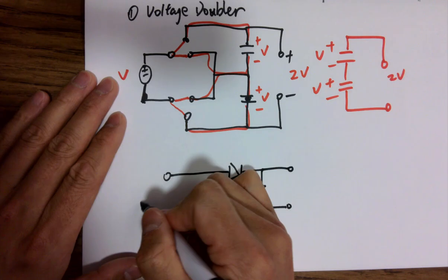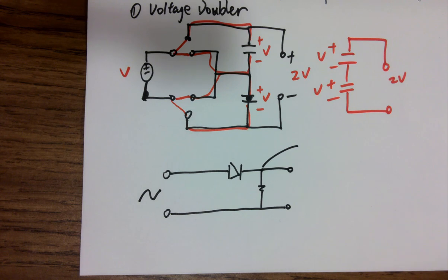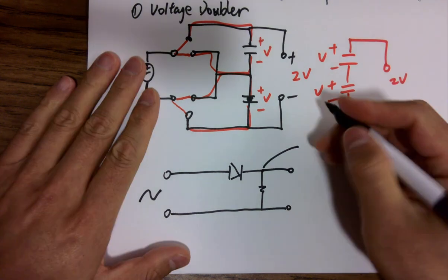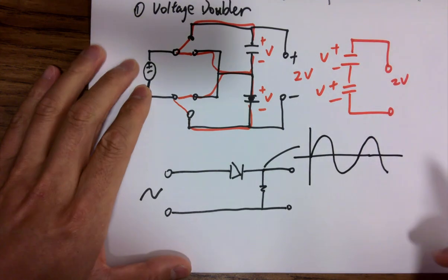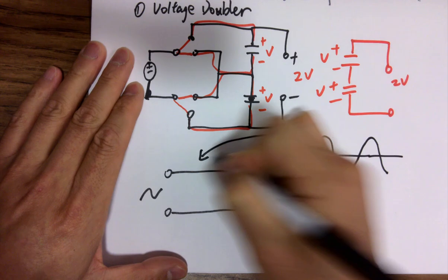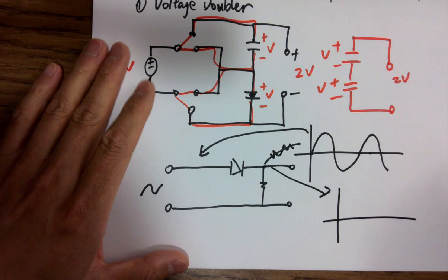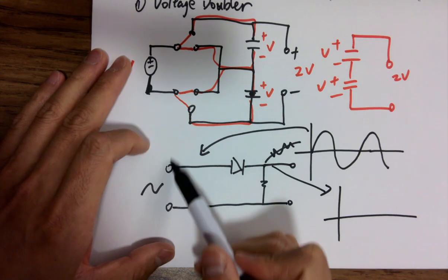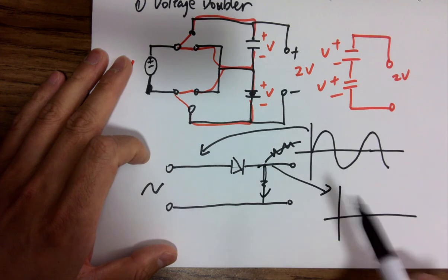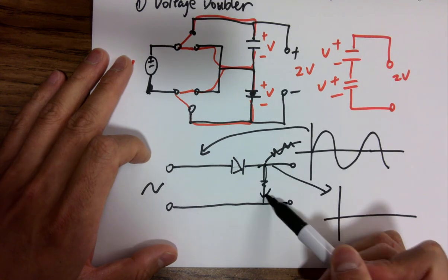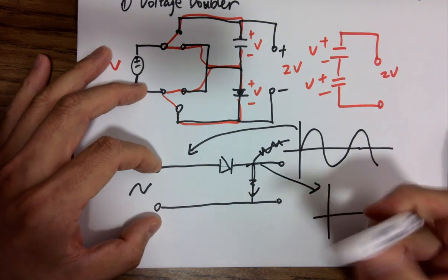If I run a sine wave, the output is going to look like what? Just a resistor here. So the input is a sine wave, right? That's V in. For V out, it'd be half, right? Because when it goes up, it goes through the diode, yeah. So it's able to go through the resistor and create a drop. So the voltage here is going to be the same as this guy, right? So you are getting the same voltage here.